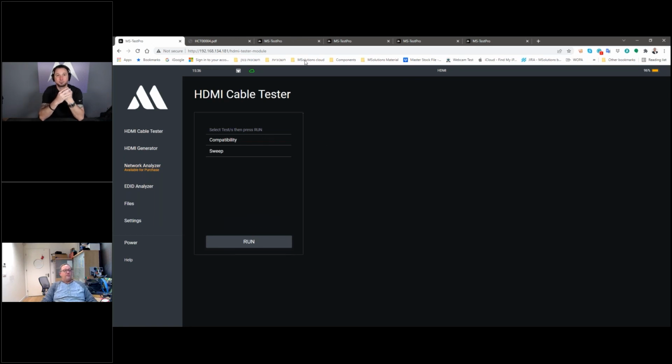Right. By the way, on the HDBaseT, we provide now, we added a lot of information about the HDMI transmission, bit error rate, and things like that. We will demo it on a different session, but we provide now, for example, on the transmitter side, what is the bit error rate of the HDMI, so that you will know from the source what is the bit error rate that the HDBaseT is receiving on the HDMI input before it transmits it over the line.